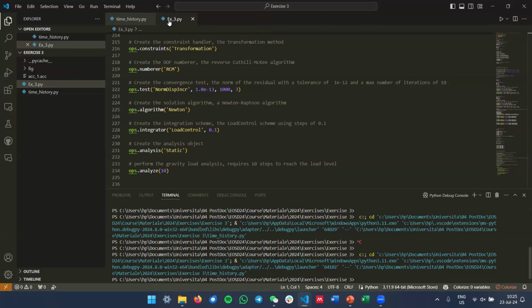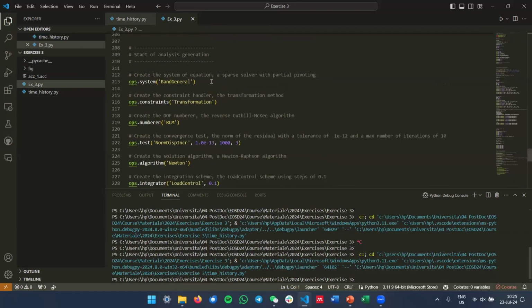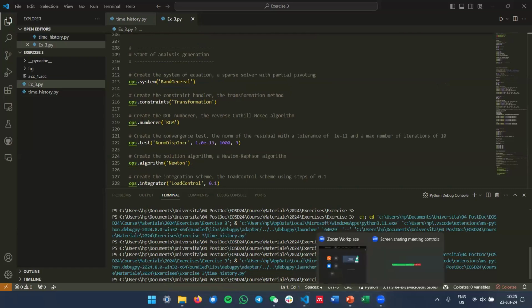Are you sure that co-rotation is not working with it? You have to think about that. LE load just splits the load in the nodes of the element. So after that, it's just a nodal load. It is an easier way for you as a user to define the loads. But if you have a problem about that, we can discuss also with Dr. Petrak later on. All right, thank you. Okay, but I don't think it's a problem to use LE load with co-rotational. But we can discuss about it.